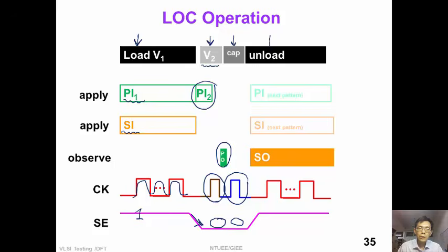After that, we unload the scan chain by holding SE to 1, and we observe the scan output.